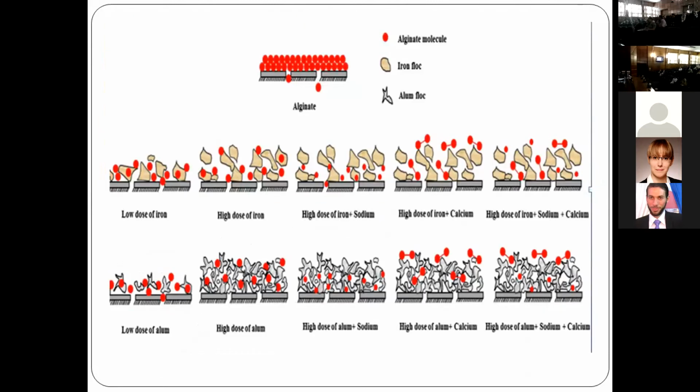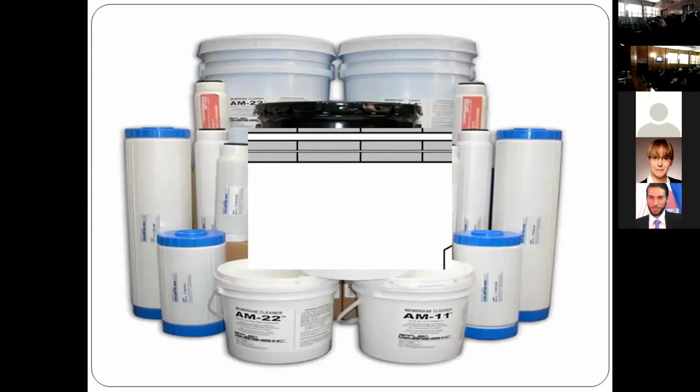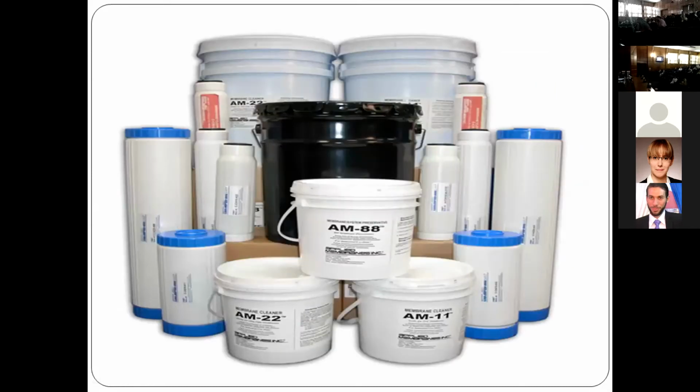Also, it agglomerates with the organics present in the water during the treatment process, helping agglomeration of these materials, whether bacteria or organics, so they accumulate on the membrane fast and increase the rate of cleaning. Overall, the performance of the system and the flux reduce with time in any membrane system, RO or nanofiltration, so we need mini cleaning all the time.